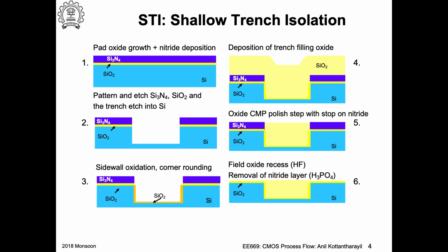And we had discussed previously that you may actually grow an epitaxial silicon layer on the top, which gives a very high quality silicon, and on which you make your devices. So the transistors can take at the most a few micrometers of silicon, the top layer. Okay, so that is typically grown using epitaxial process.